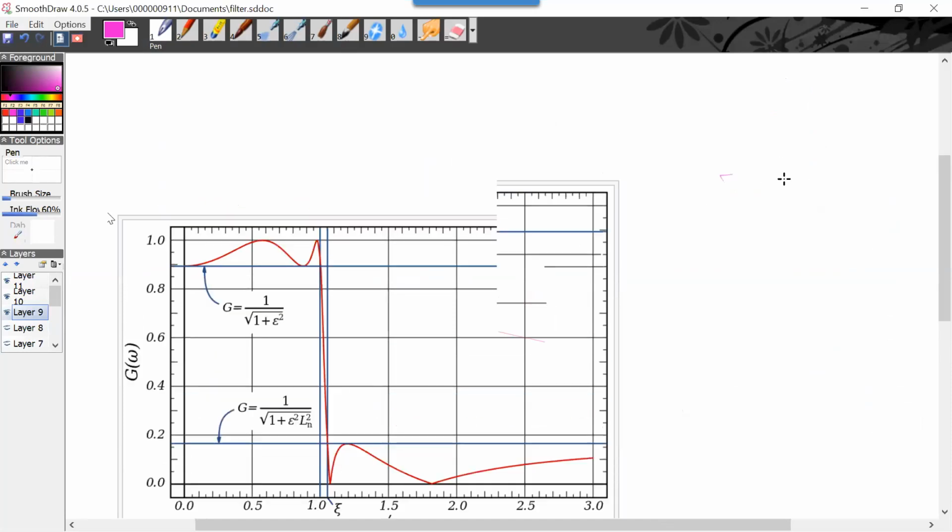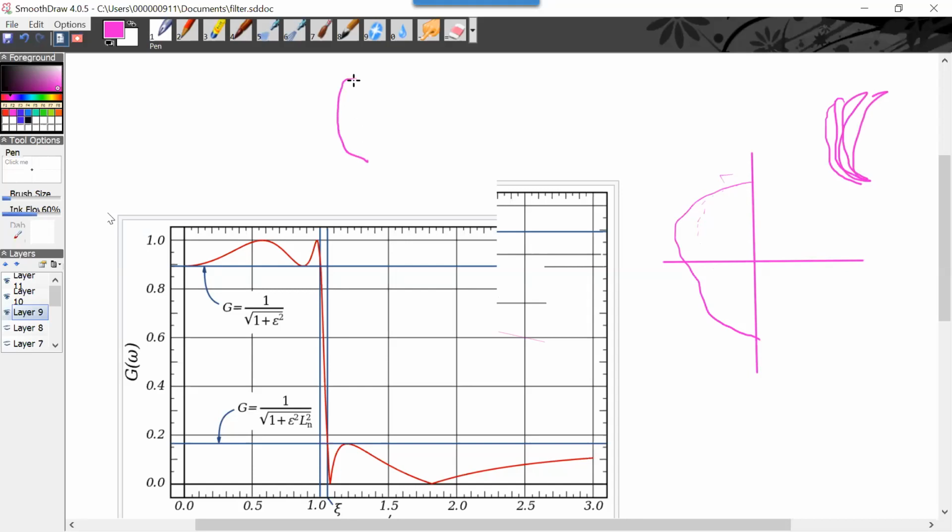And what they do is, rather than the Butterworth going on the unit circle, they're doing it on an ellipse. Sorry, that's terrible. So rather than circular, they're doing an ellipse. And yes, you get these ripples, but you also get this really sharp transition region.